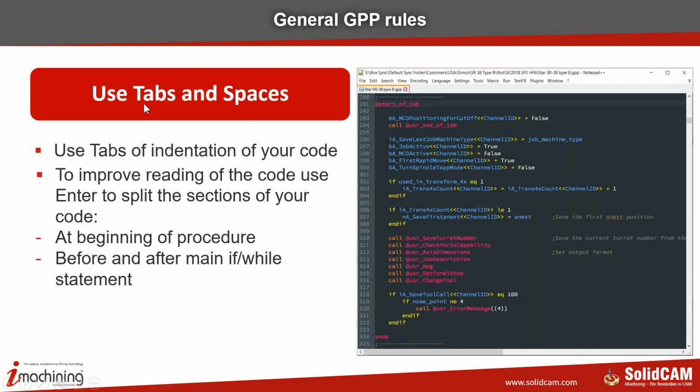The big advantage of using tabs is that every serious editor for post-processors, like Notepad++, or any free software, can have settings for the tabs. So you can change the tabs to 3 or 4 spaces automatically, and your whole post will look however you want. So just use tabs when you're defining a new block.